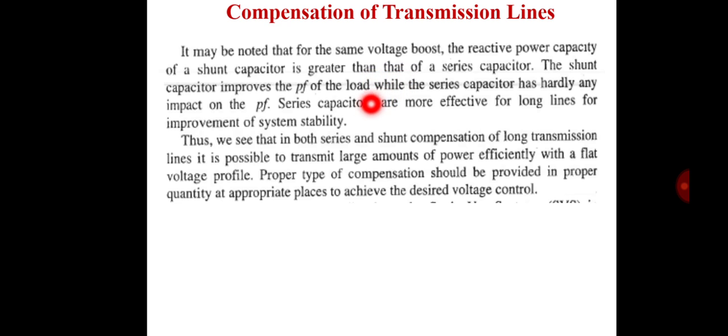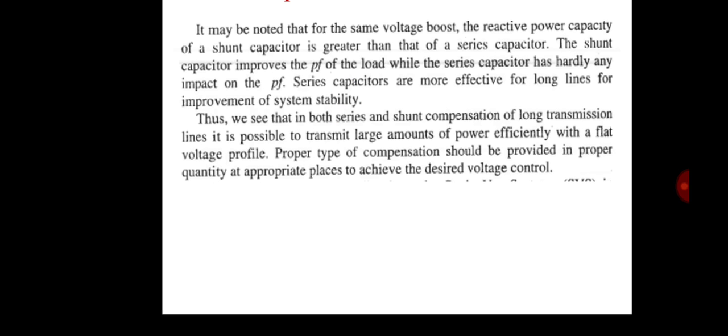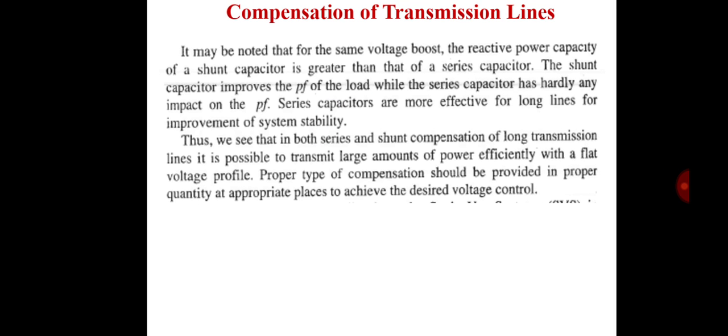So the shunt capacitor improves the power factor of the load, while the series capacitor has hardly any impact on the power factor. So series capacitors are more effective for a long line for improvement of system stability.